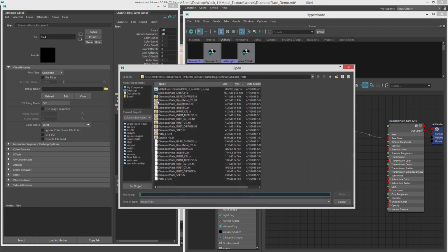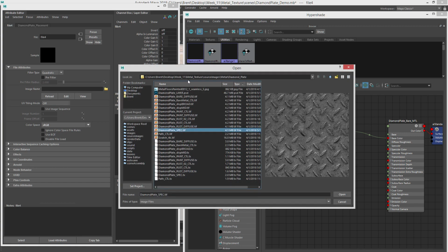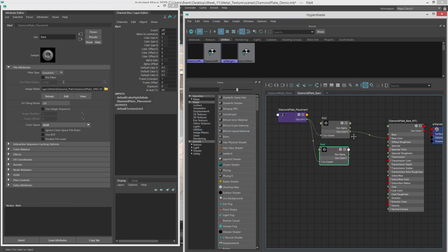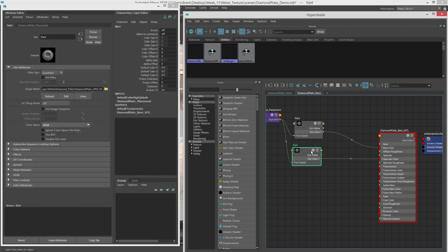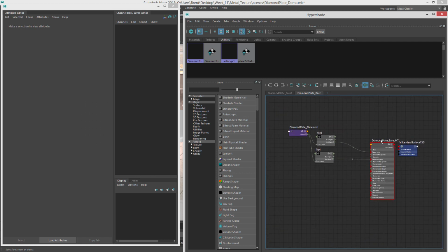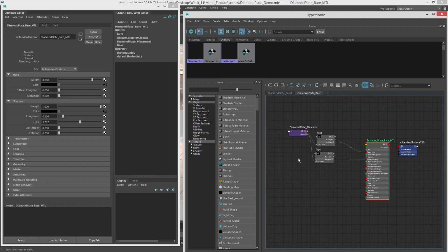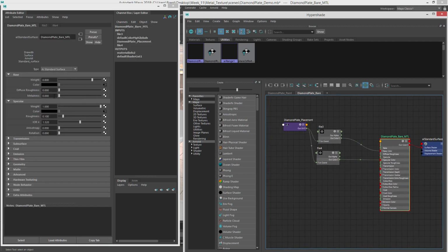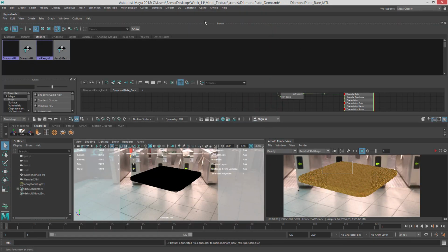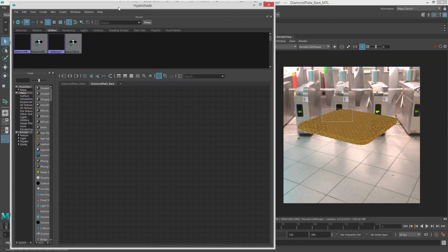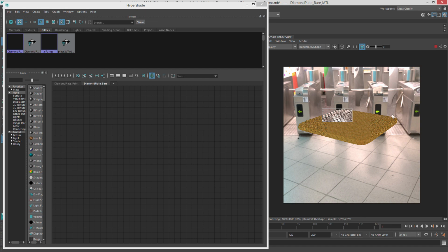All right. And I'm going to use the same spec node actually, because I can just run an AI range in there to change it from the other one. So let's take this out color, put it into specular color here. All right. And for this one, I want to use the metalness. So because this is going to be a metal object. So let's, whoops, accidentally docked that.